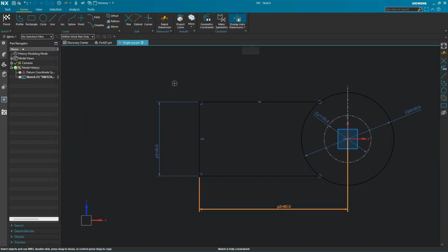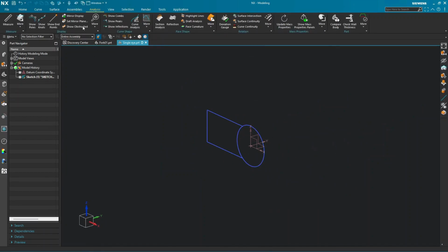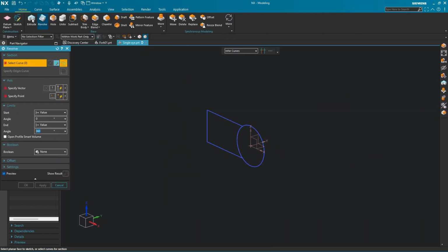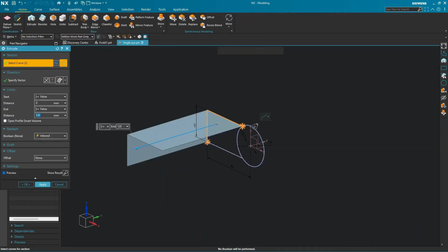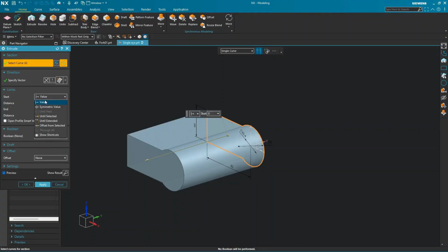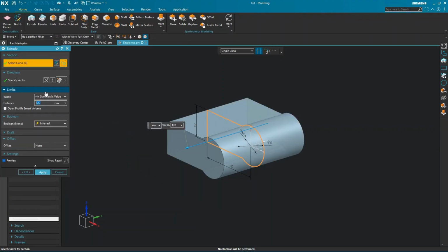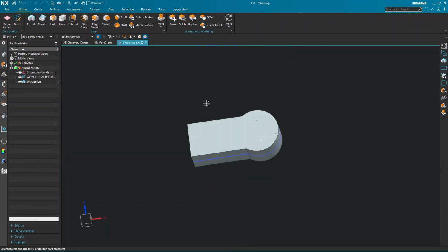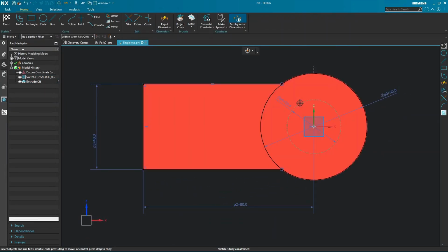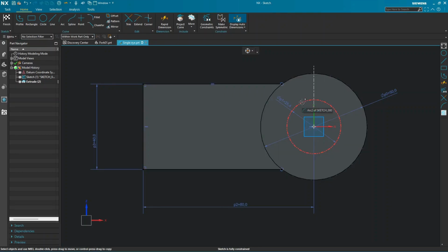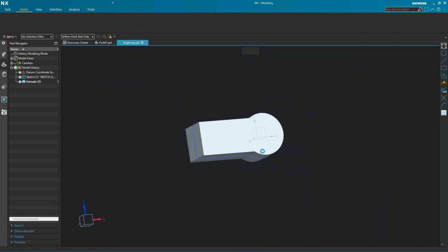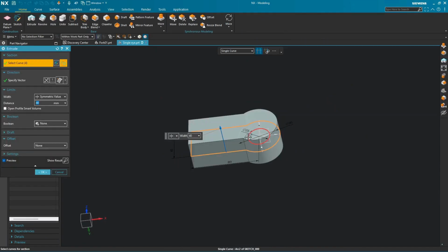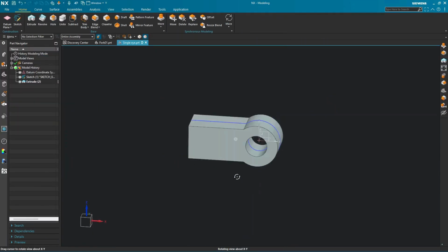Now that the fork end is ready, let's move on to the eye end, the second main component of our knuckle joint. I begin by sketching the rod axis and the circular eye profile at one end. The central hole in this eye will later accommodate the knuckle pin that connects it to the fork. After finalizing the sketch, I extrude the eye portion to the required thickness and then create the hole for the pin using a precise concentric constraint to ensure alignment with the fork geometry.